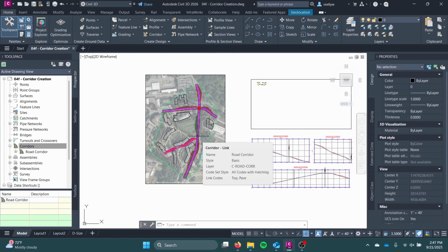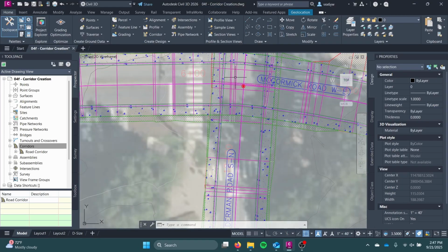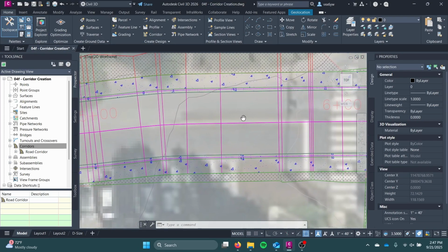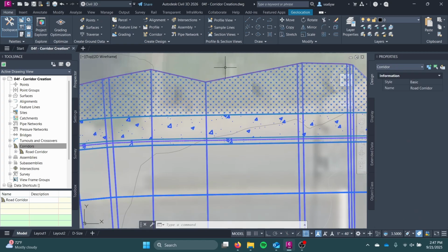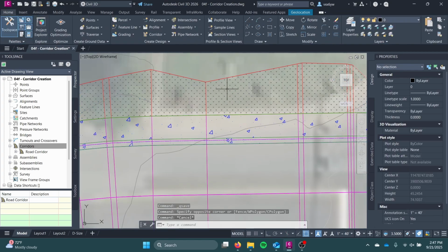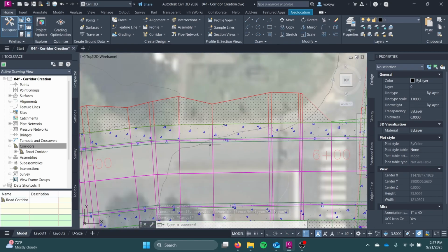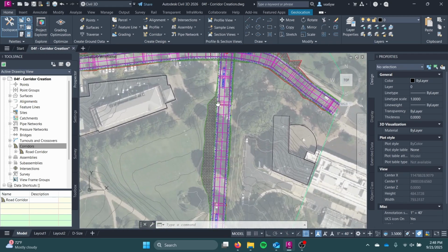The next thing I'm going to do is work on the plan view style here. So right now, the roadway is empty in terms of styling, right? You can see these different hatching patterns that show different objects. So the grass is like the cut fill. This is the little ditch we made. But the actual roadway isn't showing up as anything.